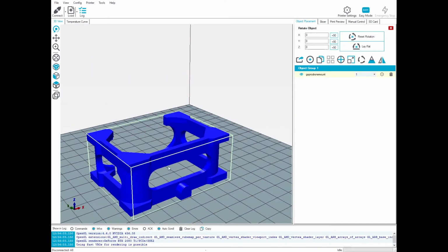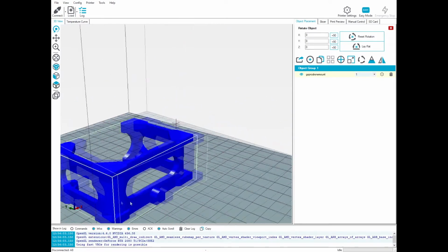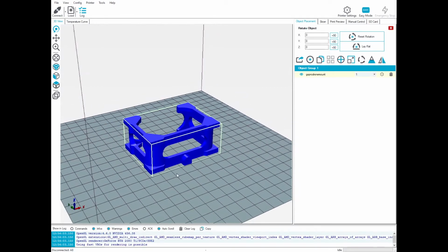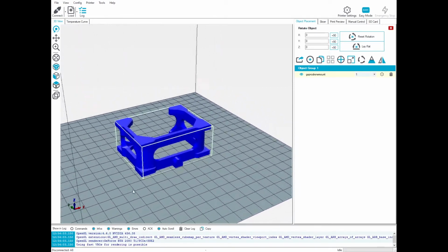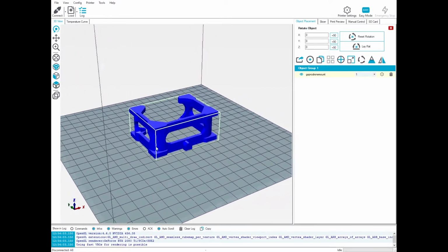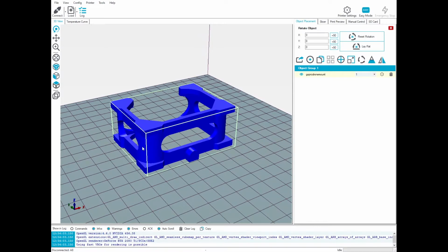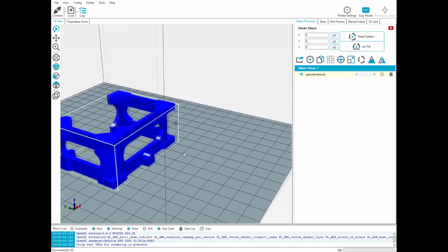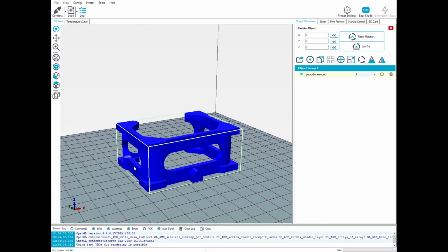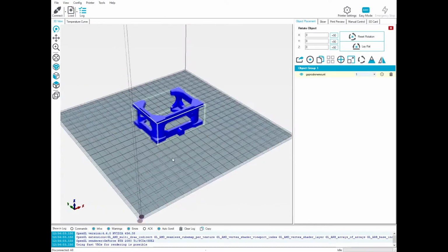And while this part does have overhangs, we'll be filling that in with a small amount of support. And yes, it was a bit of a struggle to get some of that support out of the part. Yes, the part finish did suffer for having support underneath these overhangs, but overall it is worth it to save a little bit of weight on the mount, and again to make sure it was flexible enough to put the GoPro in and out.